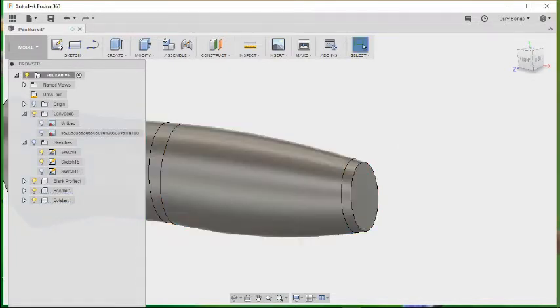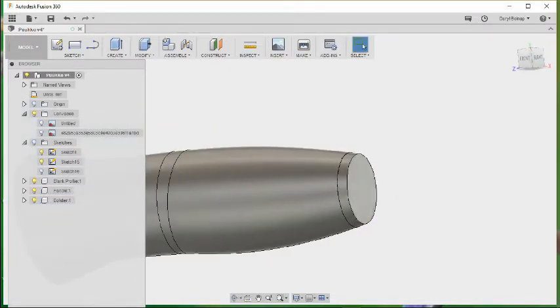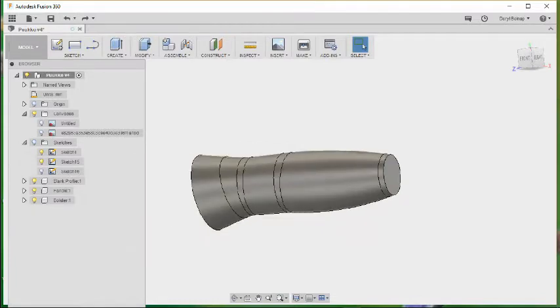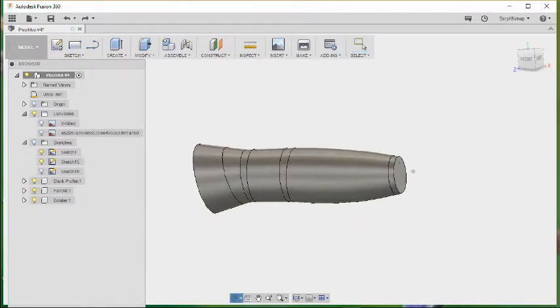So now what we have is two pieces that fit on the end of each other and not just one long one inside the other one, which would cause trouble later for when you're drawing. Alright, just escape that. So that's our little bolster that's custom fit straight onto the handle. Takes two combining steps.